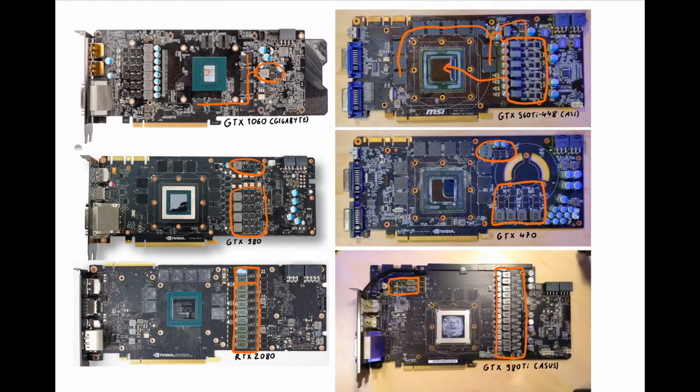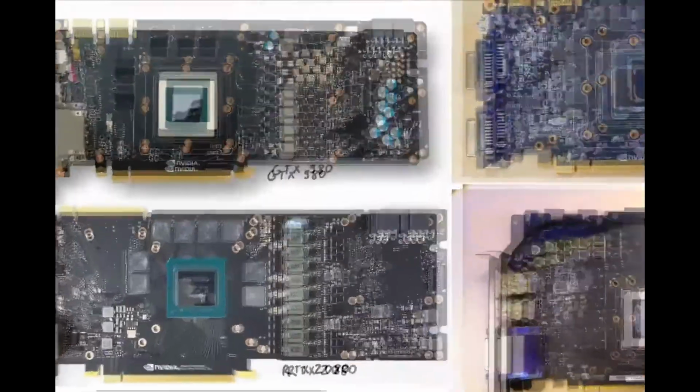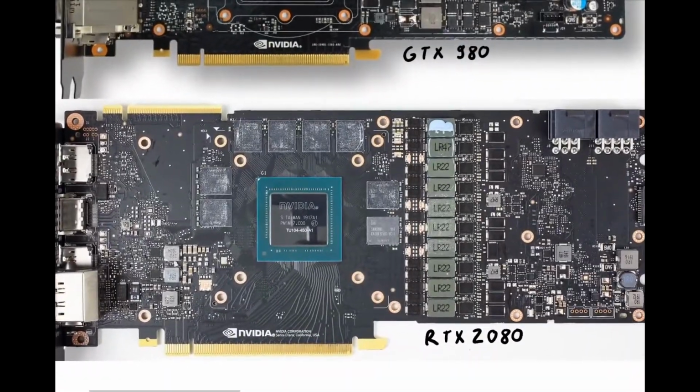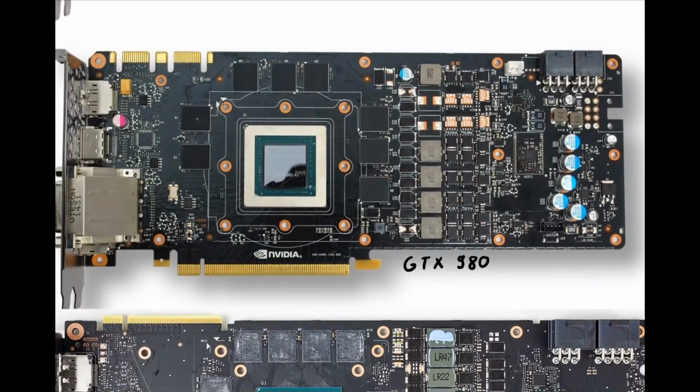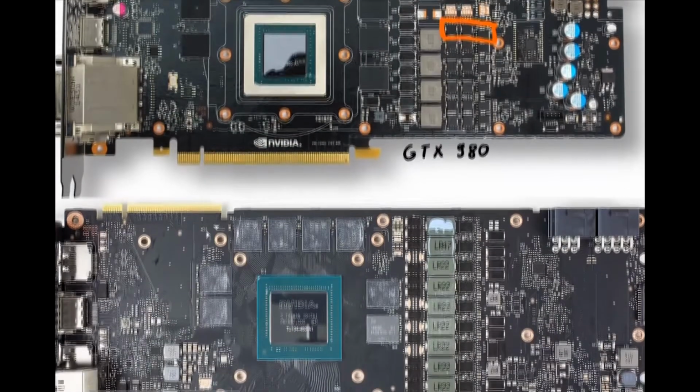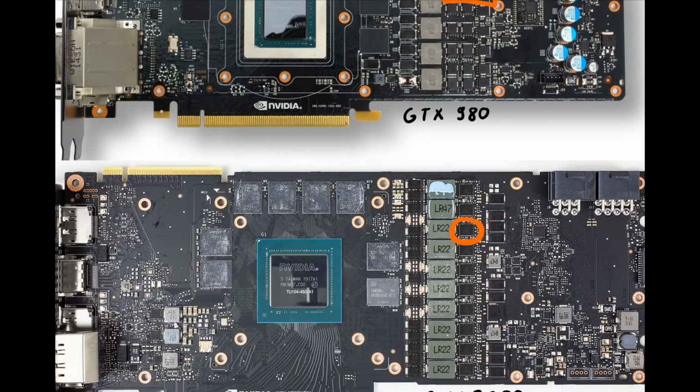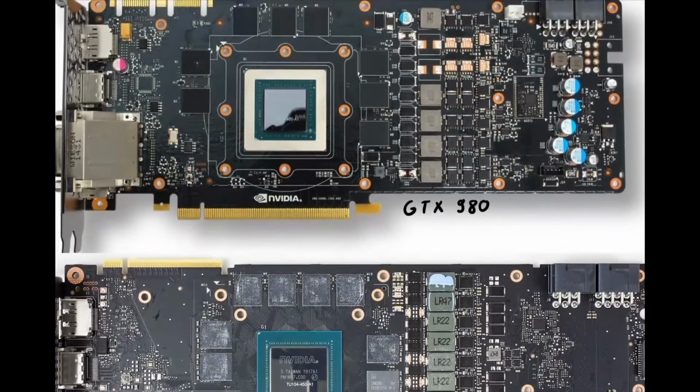VRMs look like this basically. You will always have a strip of inductors and Mosfets right next to it. Oops, I deleted the 980 there. And then there are basically these two variants. You can either have a VRM with discrete Mosfets, so in one phase, I'm gonna get to VRM phases a little later, you have 3 Mosfets, for example, or you have one power stage. The power stage integrates at least 2 Mosfets, a high side and a low side. That I'm also going to talk about later.